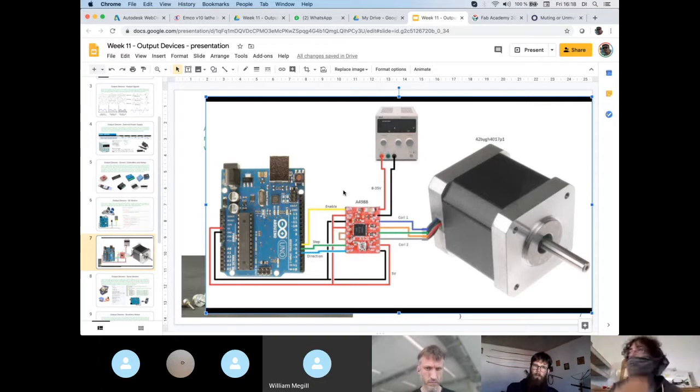In machines, typically the enable is used so that whenever the machine is not moving, you can disable the motors and cool them down, because if the motor is enabled and current is passing through it, it will become slightly warm. So you can save a lot of energy by enabling or disabling the motor. You can also think about the Zig laser cutter, for example, where you need to move the axis by hand to take the home position.